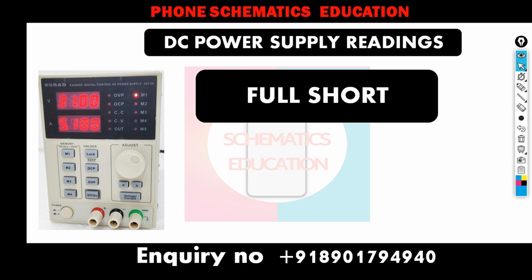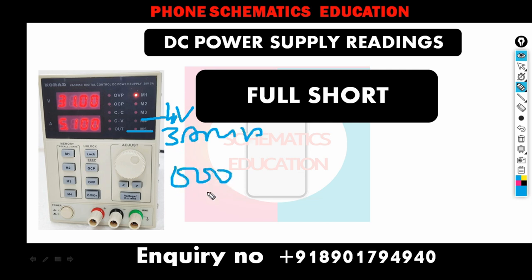A full short. The phone comes to you with a full short. How to identify? When you connect the DC power supply to the motherboard, let's say you set 4 volt and 3 amp, it shows 0 0 at first when the DC power supply is off.